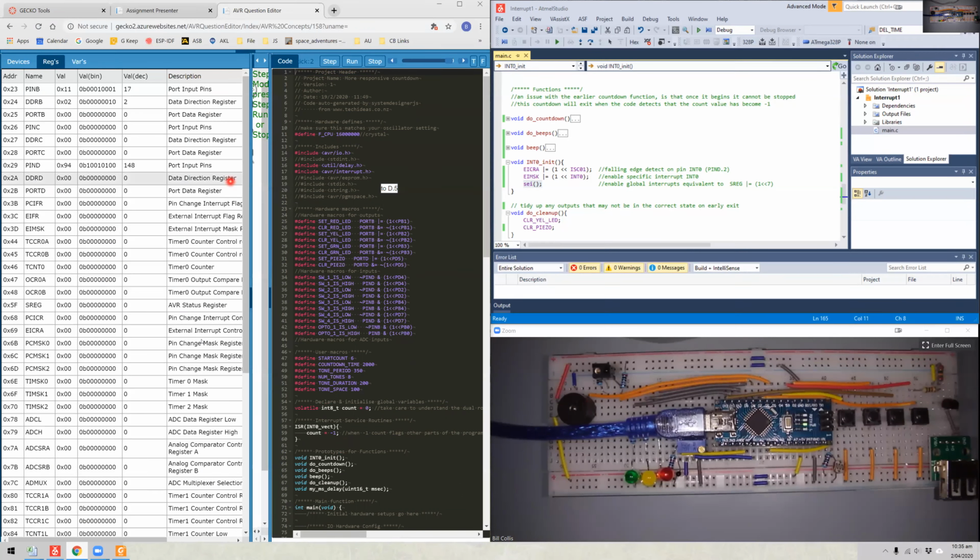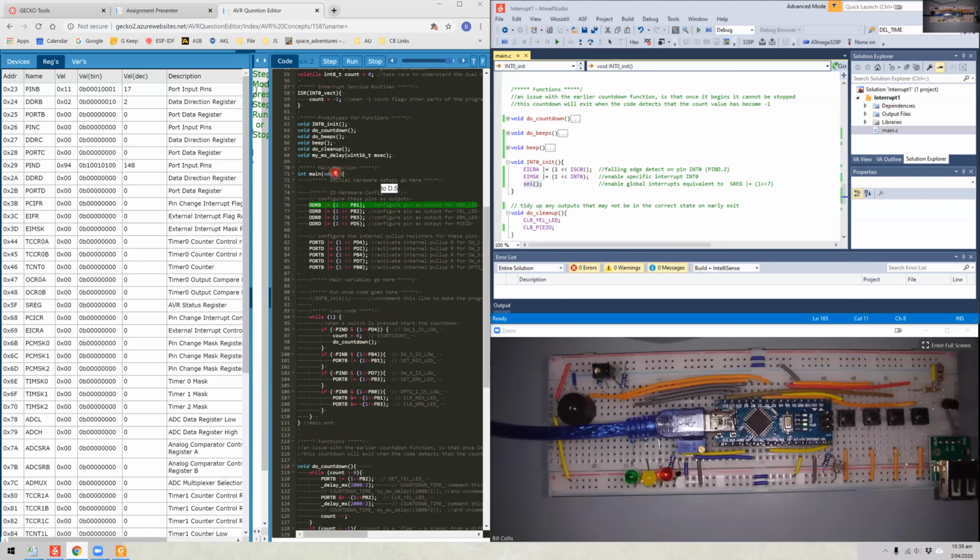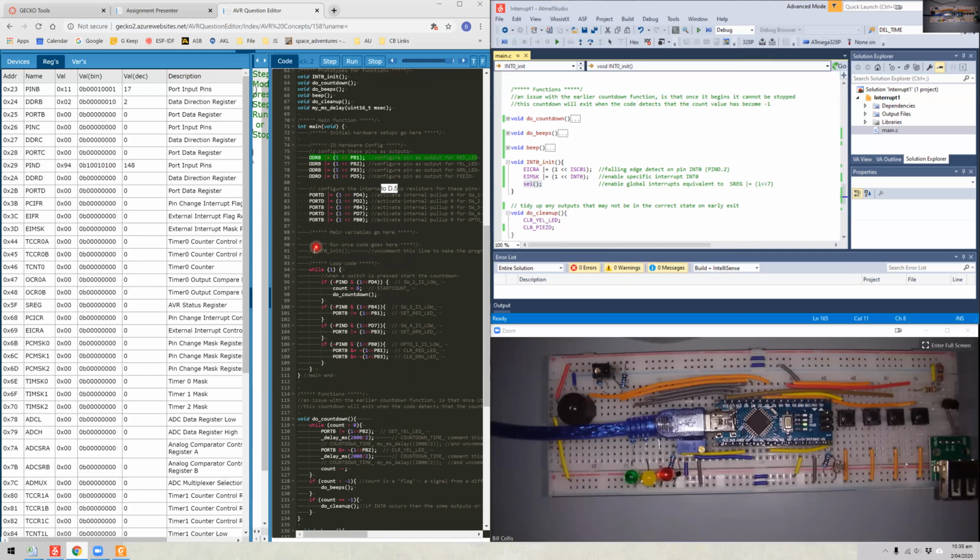And the first thing it does is it sets all our registers to 0. These port input pins are actually high at the moment because those have got switches connected to them, so that's why they've sensed them as high. And as we step through the code, actually it's not going to work because I haven't uncommented this to do the initialization. Let's step through the code now.